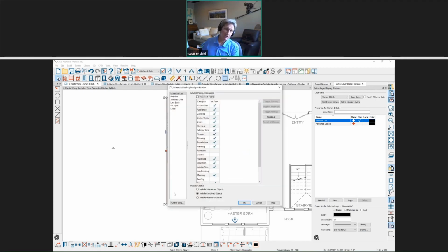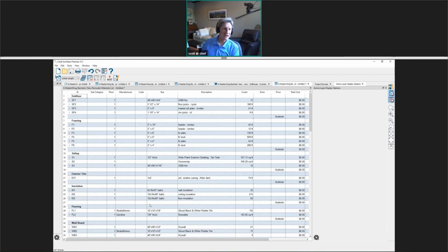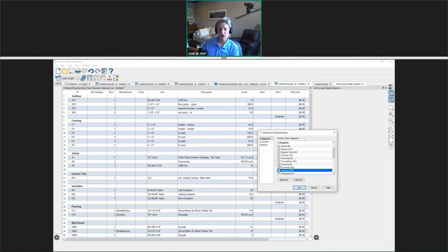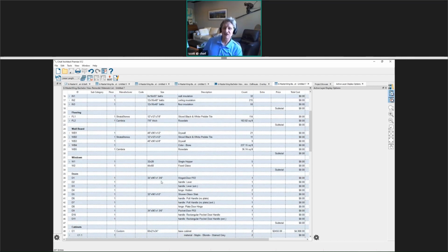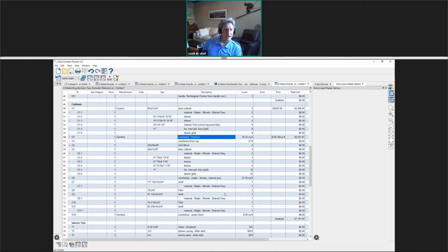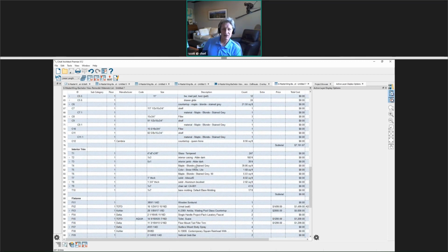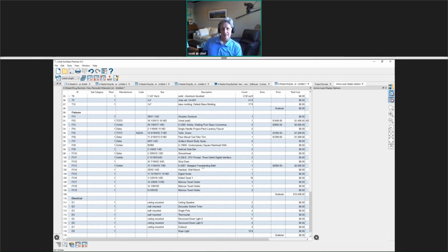And then we regenerate it. So let's regenerate a new list. And then you're going to see, I apparently didn't turn framing off, but we could easily turn that off. Go in here and just pop off the framing, just for one example. Now I'm getting just that list. And if you come down here, you now see that I've got the larger cabinets. I've got countertop materials in here. Each one of those elements is being included, and then you can dial in exactly what you want out of this materials list.